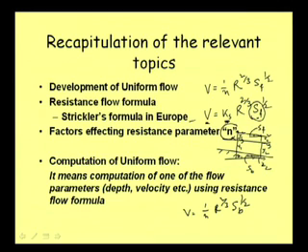So, while doing this computation of uniform flow, we need to understand that though we specify some N value, in reality, to have a more accurate calculation, we should know that this value will change, and when some changes occur, we need to change our N value accordingly. Well, then we started with computation of uniform flow.